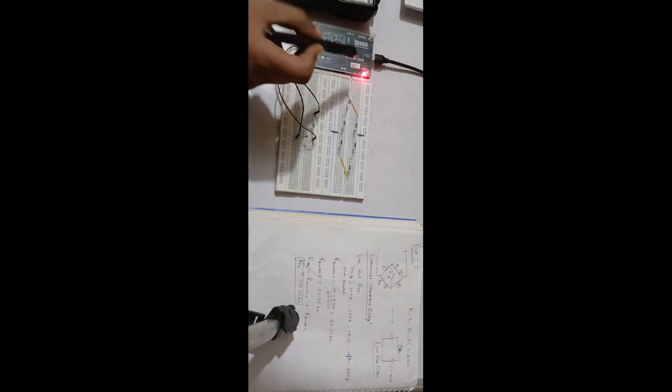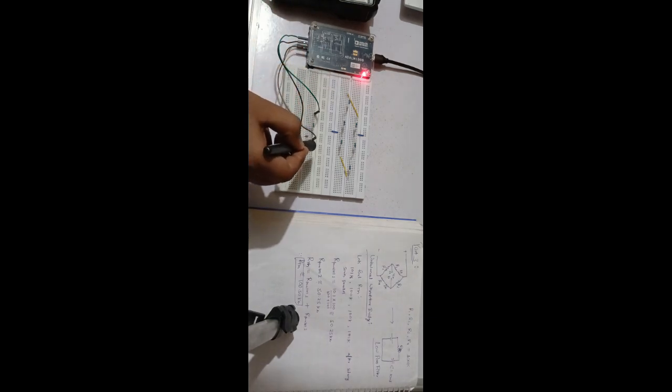Through the ADALM1000 we have powered channel A to the input of the resistance and node, and channel B to the node of the resistance, and in addition to the capacitance there is a ground. Now we have to measure and record the output voltage using this multimeter, and through our laptop screen or on the Pixel Pulse app, how the peak to peak voltage varies with frequency.